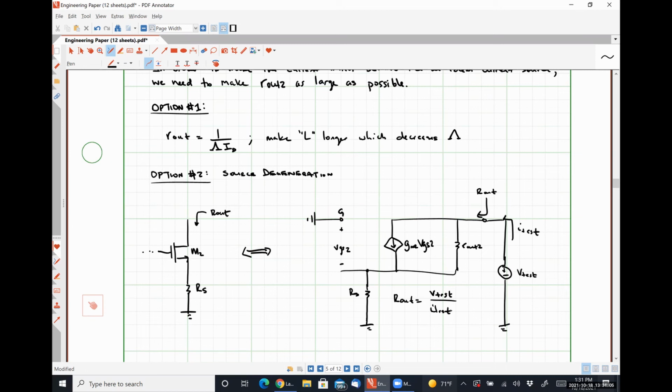So, a couple of things that we can observe here. The first of which is that the voltage drop across resistor RS is VGS with this polarity, right? So the source is at the minus sign, and because our gate terminal is at ground, then anywhere else we see ground is also the positive polarity terminal for that.